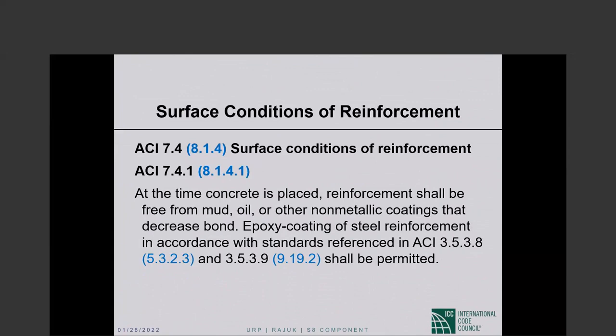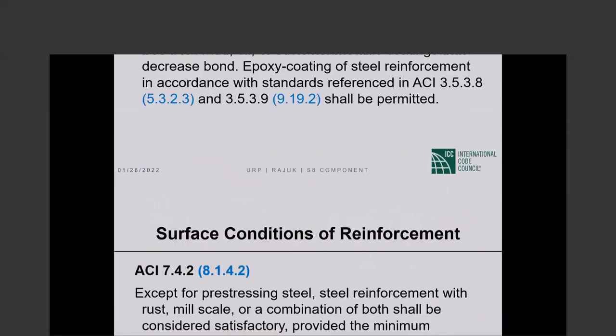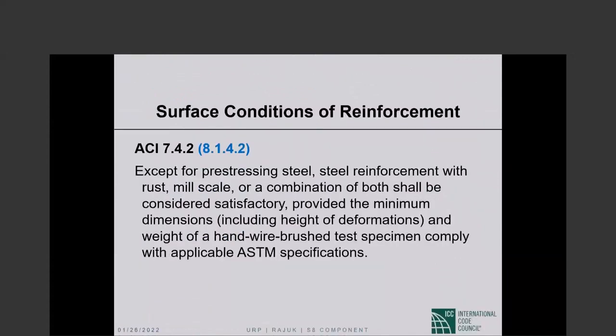Surface conditions of reinforcement. At the time concrete is placed, reinforcement shall be free of mud, oil, and other non-metallic coatings that decrease bond. Epoxy coating of steel reinforcement in accordance with certain standards shall be permitted. Except for pre-stressing steel, steel reinforcement with rust, mill scale, or a combination of both shall be considered satisfactory. There's absolutely nothing wrong with rust.